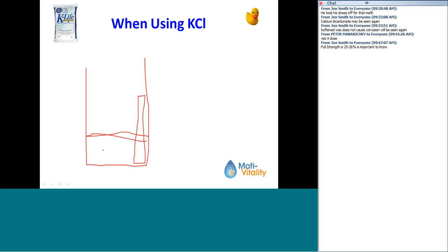But basically, you put the salt in. Here's all the salt up here, and it drops down. But what it does, so here's your water level on the float, is it forms this hardened layer down on the bottom, which gives you a false bottom of the brine tank. Okay, so it can form this hard layer down here. And that gives you the false bottom, which means that the salt's still dropping down, the potassium chloride's still dropping down, but essentially you have less water in there because the float level is still right here. That's still the height. So you can take 2 or 3 inches off the water level.